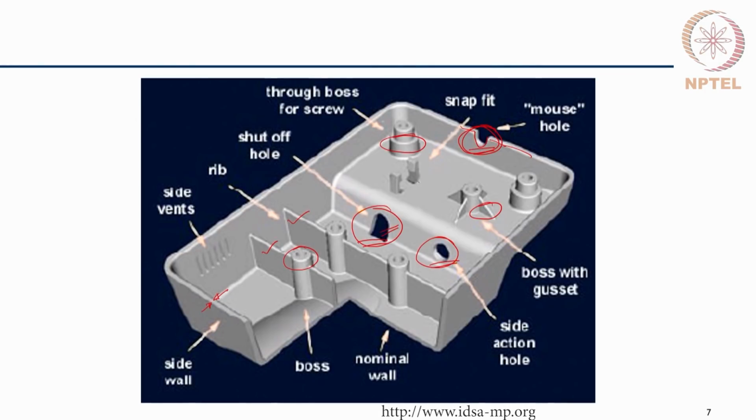We also see one feature here, this is called a snap fit feature. Most of the times in plastic components we try to avoid, to the extent possible, the screws, and snap fits are encouraged because that reduces the assembly time when these components are assembled with other structures.